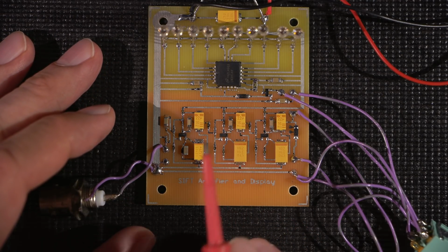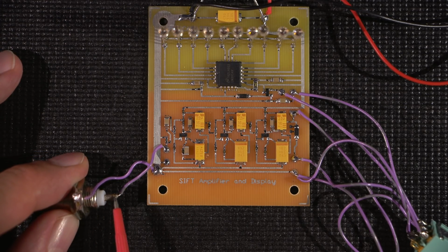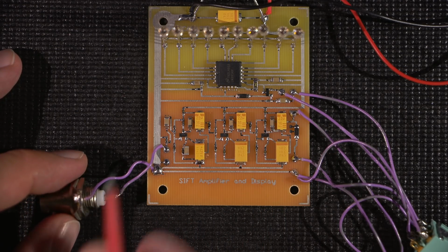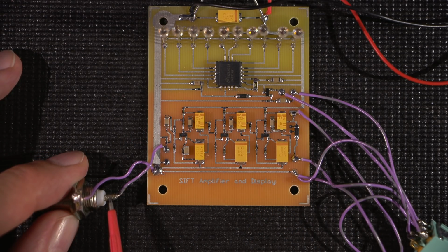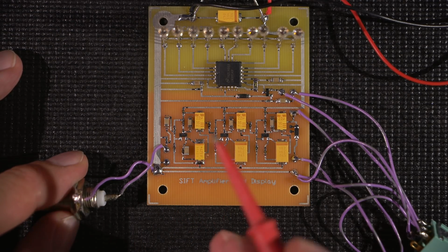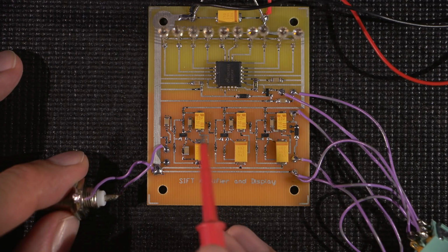So again, times 1, AC coupled oscilloscope. I'll give you an example. If you're using an audio amplifier and you're going to be testing an audio amp, you'll have plenty of signal from your signal generator to look at on a normal oscilloscope. You want to verify that you're seeing something right at the signal generator. Because if you can't see anything here, what's to say you're going to see anything there when you're troubleshooting? Maybe your scope's not set right, maybe there's something wrong. So you want to be able to see amplitude at this point so that when you're troubleshooting through the rest of the circuitry, that amplitude is visible.